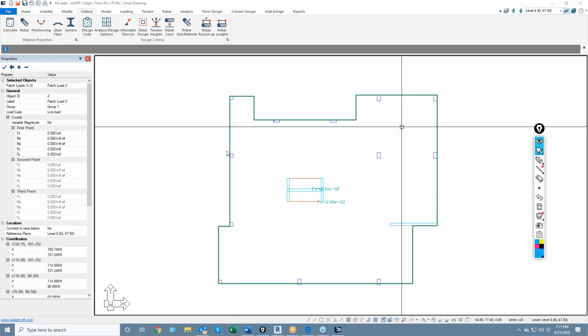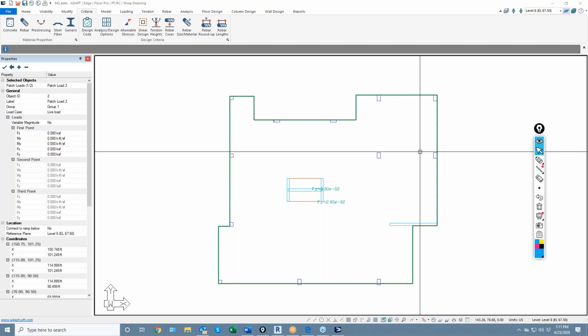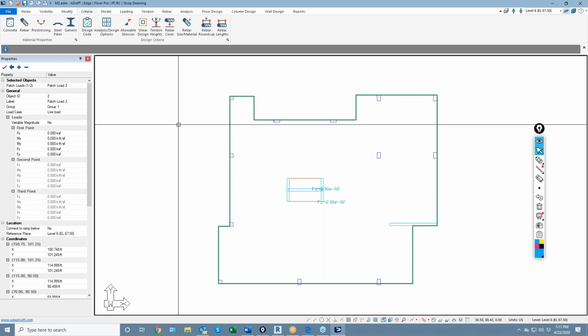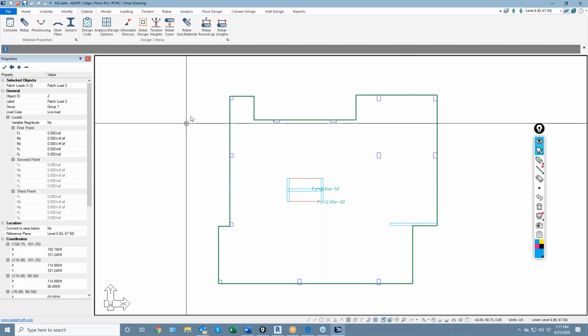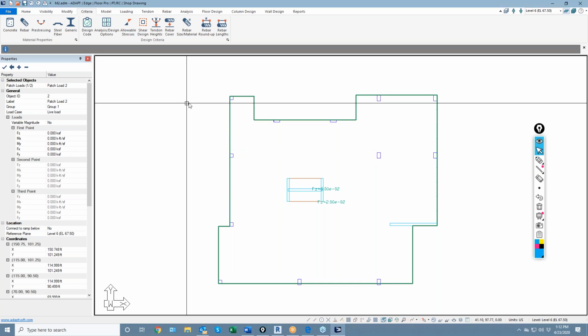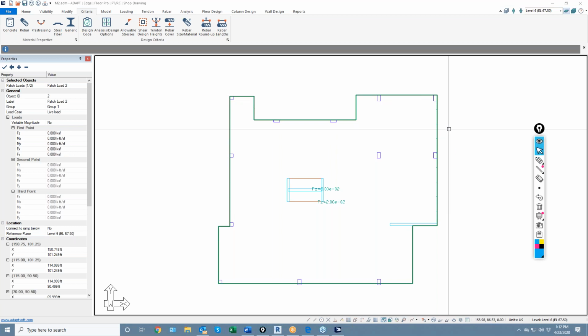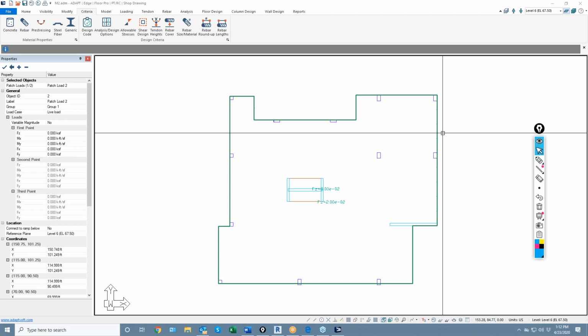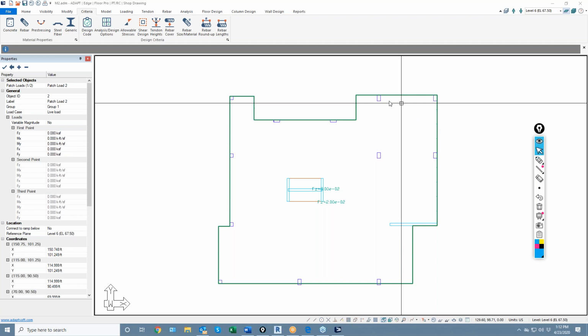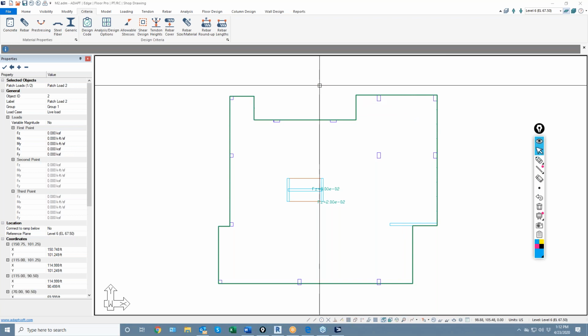There's a quick question on live load reduction. Can they overlap, or do we need to keep them separated? Pavel, I don't know if you're referring to the actual subregions overlapping or the loads themselves. Yeah, the loading can overlap. It's just if they do overlap and you have a subregion that has two loads in that subregion, then both loads would be applied in the subregion. But you can only assign one load to be patterned.